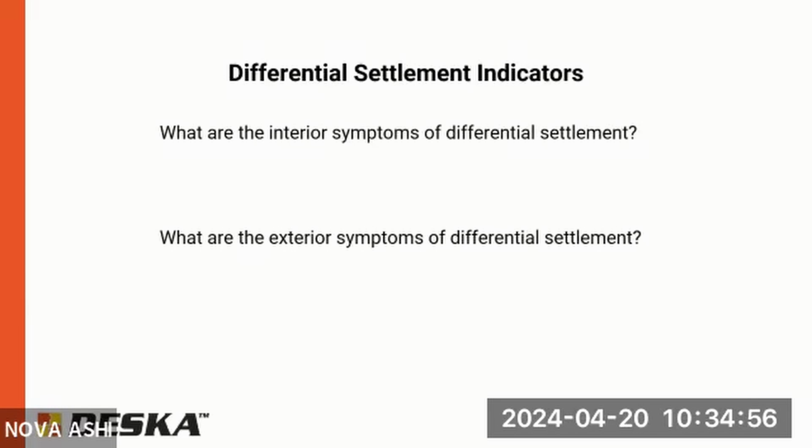Yeah, I'm talking about once it's encapsulated, vents are closed off, right? Because what we're usually telling people is to make it a conditioned space. But if they can't make it a conditioned space, so their HVAC is in the attic, their vents come down, they're not getting it down to the crawl space. Does the dehumidifier solve the problem, or do they need to leave it vented? Yeah, you could go either way. I would not recommend encapsulating and closing off the vents and then not conditioning it or putting a dehumidifier in, because there's no airflow. Moisture will probably build up.